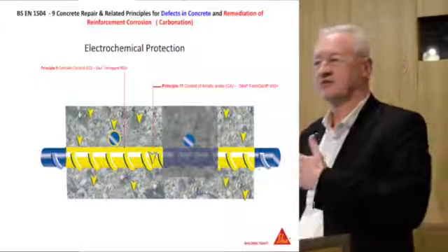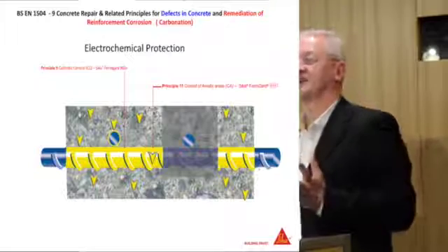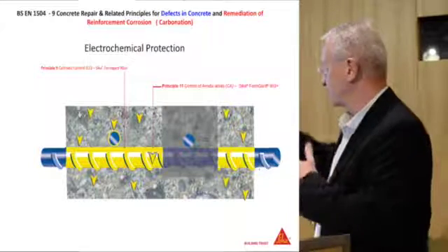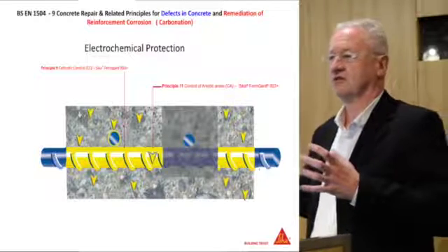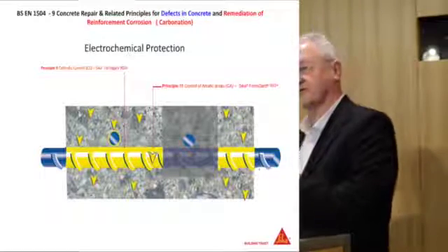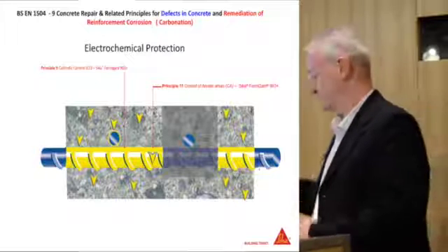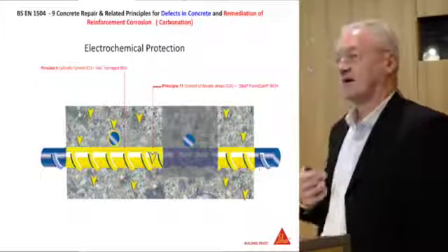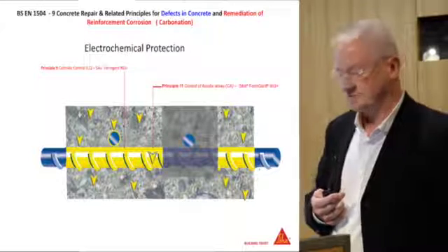but also to try and stop moisture and oxygen getting through, so we need to dry out the concrete. So we're looking at a synergistic effect of not only the Ferrogard or the inhibitor, but also the coatings as well, drying out the concrete. Bring these corrosion rates down to an acceptable, controllable level. When we've got chlorides, then obviously it's a completely different game altogether.